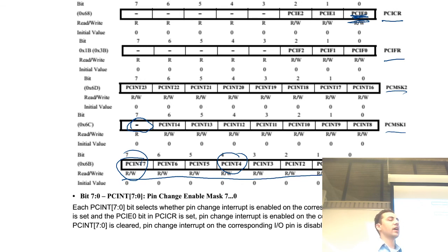Okay, so it gets kind of interesting when you have three pins that are all going to cause pin change interrupts. They're all triggering the same interrupt service routine. Then you have to figure out which one triggered it. So you have to know what their previous state was, and then you check their current state. You have to check for rising and falling. There's a little bit more to it. If you just want a single one, it's not that big a deal, but those are the differences.